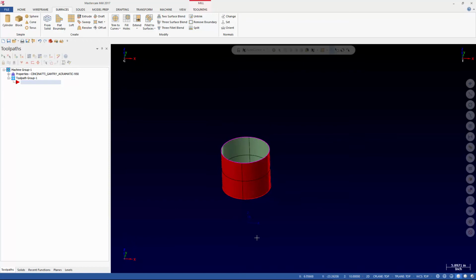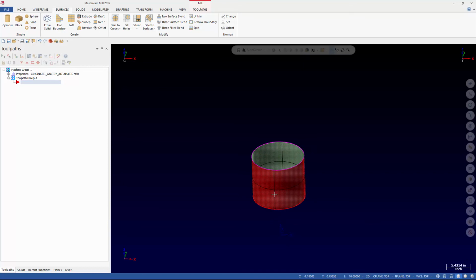The reason is that we want to simply be able to tilt the A-axis 90 degrees, approach the cylinder, and then cut using the C-axis only. If we were to start the cut at X positive, we would actually have to rotate C to be able to get to that position on the machine.